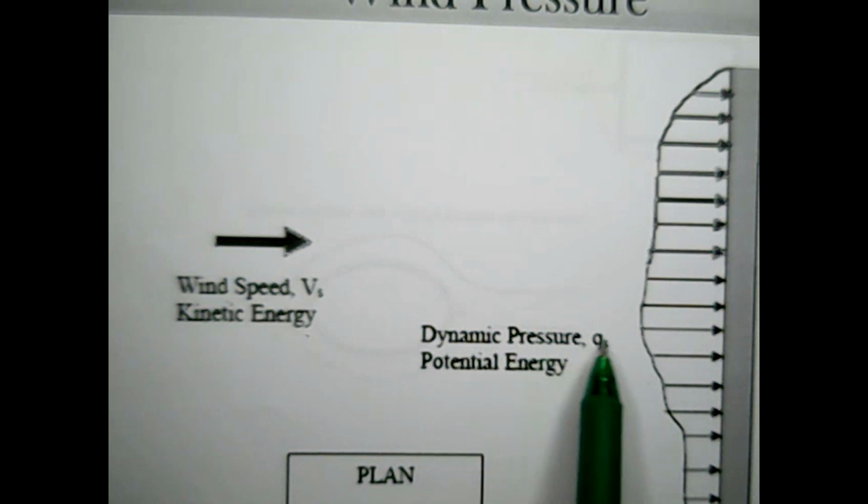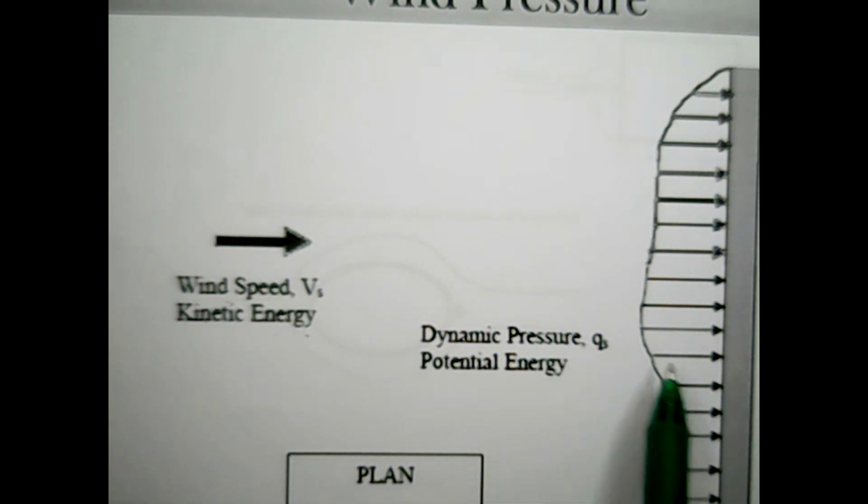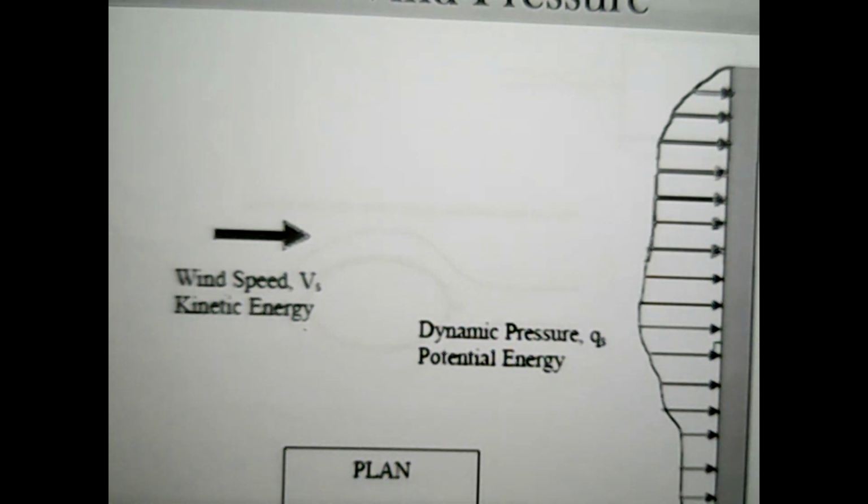The dynamic pressure is the wind load. This pressure acting on the building is what we call the wind load. Usually, the wind load is measured in unit Pascal or kilopascal, and usually acts normal to the wall, the angle, roof or other surfaces of the structures.